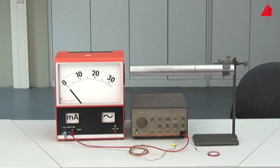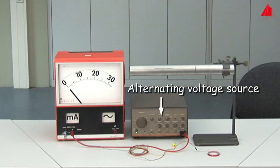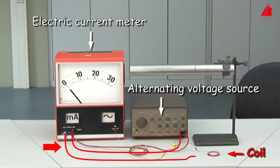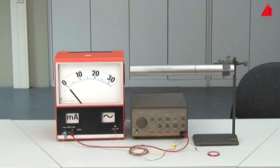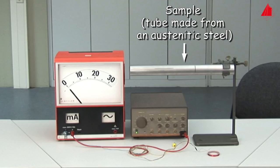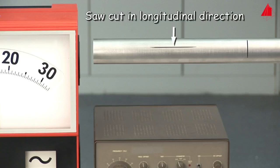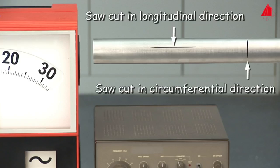In eddy current testing with coaxial probes, the coils are either pushed coaxially over the workpiece or pushed through the workpiece. This is our simple test setup: the alternating voltage source, the electric current meter, the coil. Cables lead from the alternating voltage source to the electric current meter, then to the coil, and back again to the voltage source. Our sample is a tube made from an austenitic non-magnetic steel. We have purposely machined two cuts through the tube wall, one in longitudinal direction and one in circumferential direction.